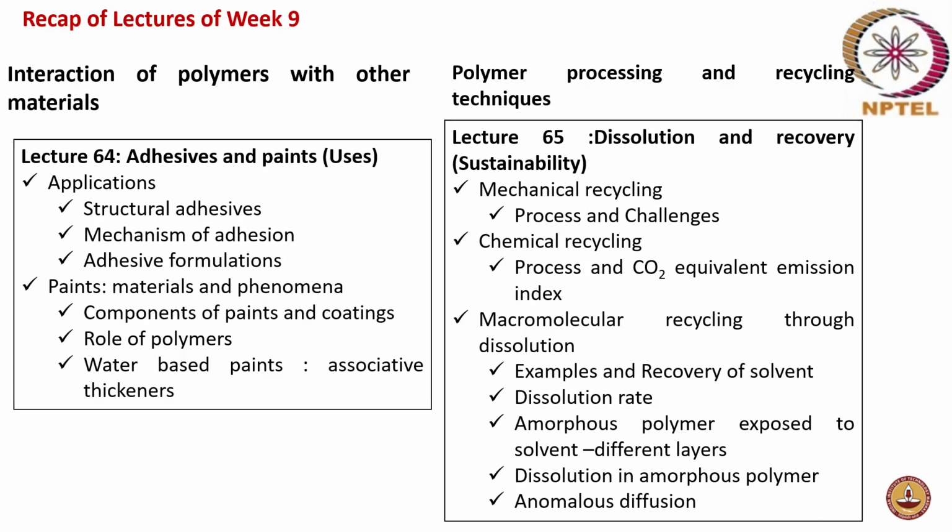In the first layer, there is a liquid layer. This will have a large amount of polymer which is already dissolved in the solvent. Since your solvent molecule can diffuse little by little only, the next layer will be a gel-like layer, with entangled polymer and a large amount of solvent.